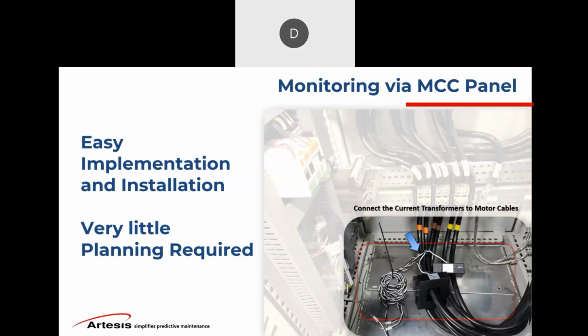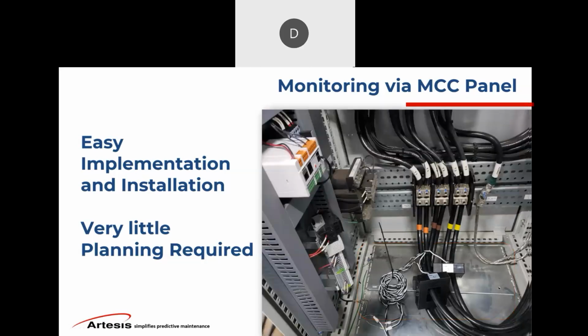A common question is if there's a VFD. Yes, we can monitor VFD-driven equipment. We put it on the load side and not the line side. So on the load side for anything that's in that cabinet, arrow pointing towards load, and we provide you with about 6 feet of cable so you have plenty of room to install the CTs. So now we have the voltage, the current, and then it's just communication out. The power supply is 120 volt from the cabinet. So again, very simple to install, and very little planning to get them implemented.